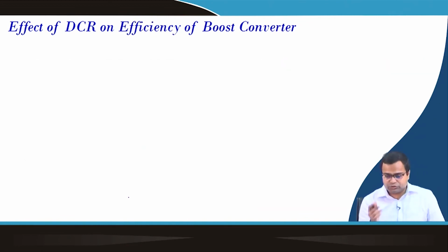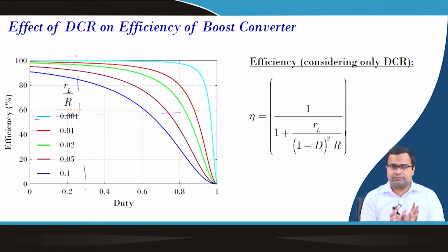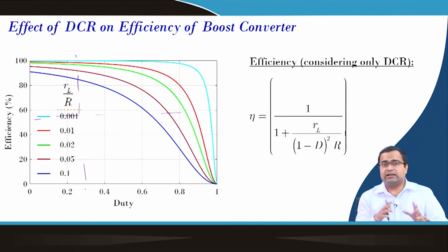Okay. So, the efficiency of the boost converter also will get significantly affected by this parasitic drop, and if you tend to achieve higher gain, you will lose efficiency like anything, and nobody will do that because we want to achieve efficiency of more than 90%, which is achievable for lower duty ratio operation. So, you have to be very careful about the selection of the voltage gain, and there are multiple research papers which actually propose to increase the voltage gain with higher efficiency, which the ordinary boost converter cannot achieve.